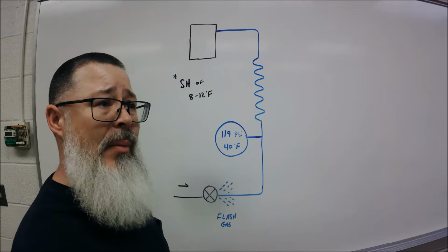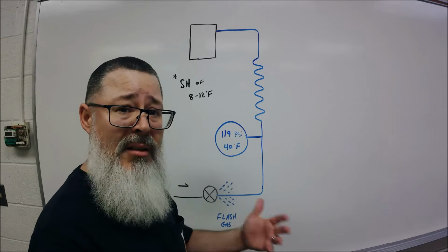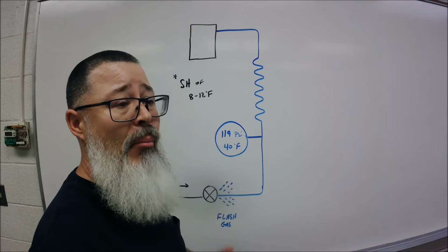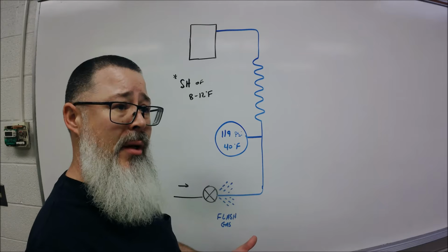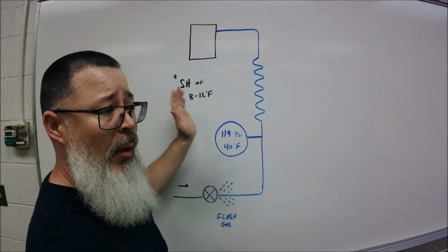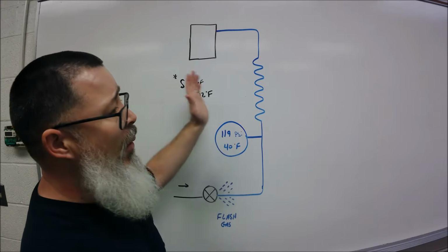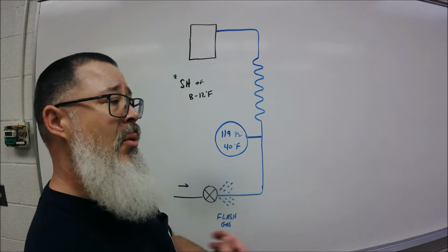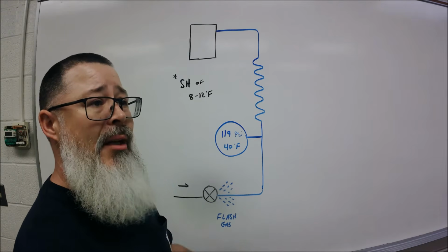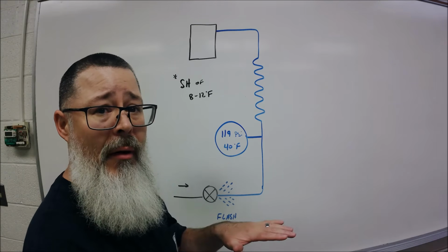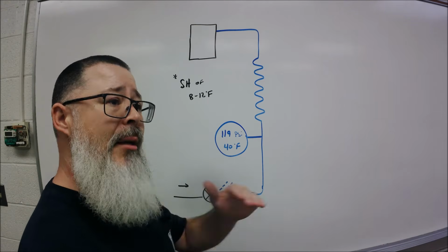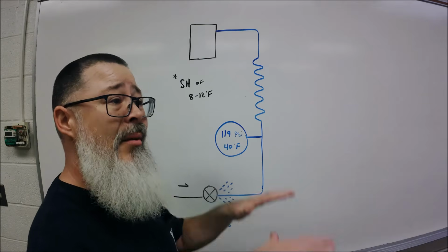That is what a lot of people will say the coil is working at, the temperature at which everything is happening. It is in fact a boiling thing, because liquid refrigerant is absorbing heat. We have 400 CFM of air hopefully going across our evaporator coil, and it's bringing in the heat from the house or the space or whatever office, and it's keeping that saturation point and that pressure there. The heat being brought in by the fan keeps it there. If we didn't have the heat, it would drop.